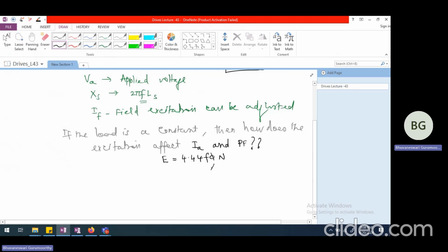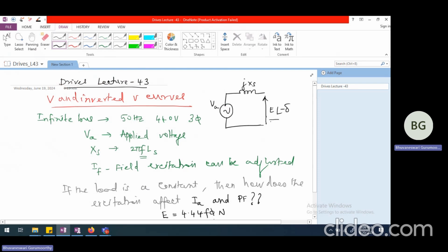So in one sense, we can say the excitation voltage will be proportional to flux, which is also proportional to the field current. And generally in a synchronous motor, when we are giving sufficient flux from the field side, that is the rotor side, then if we are delivering a particular torque, electromagnetic torque TE, it may just draw a current from the power supply, which is IA, just sufficient to produce the torque by interacting with the flux.